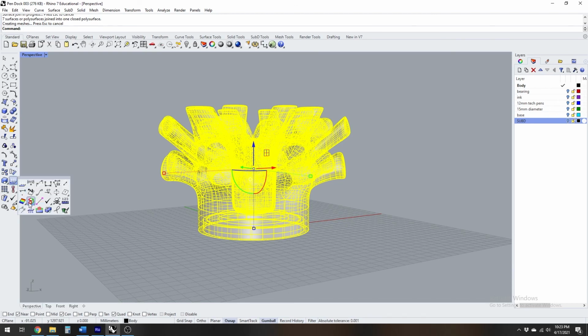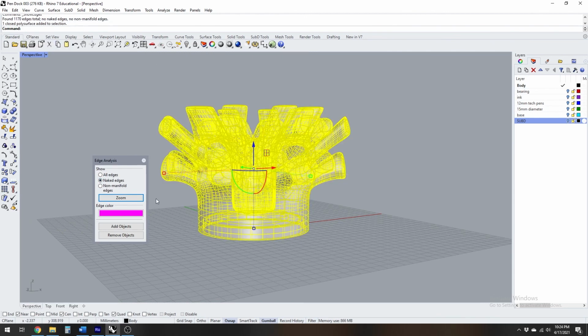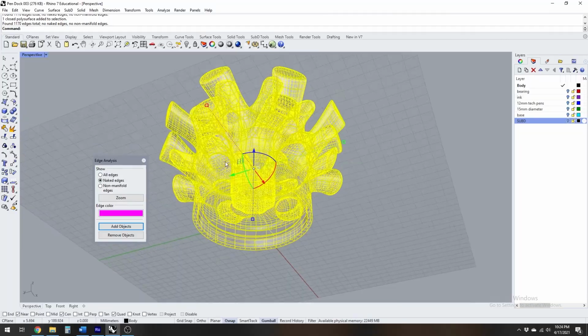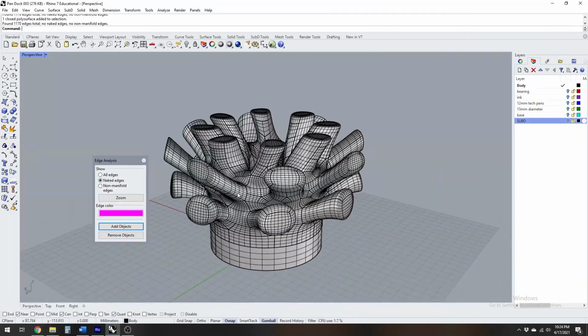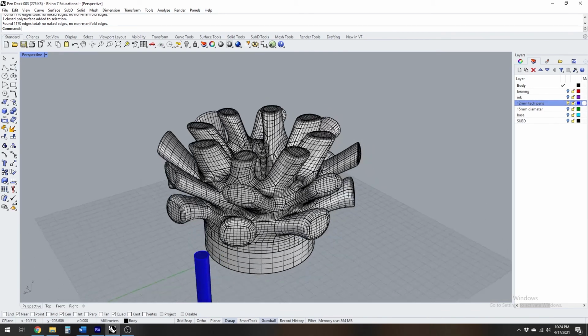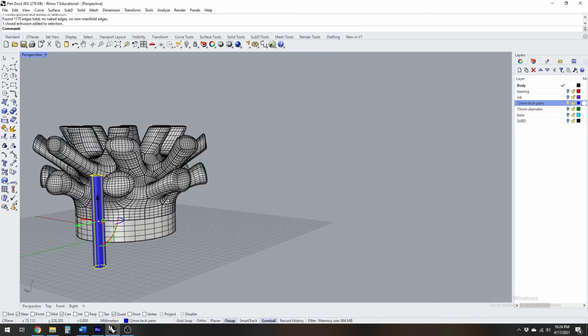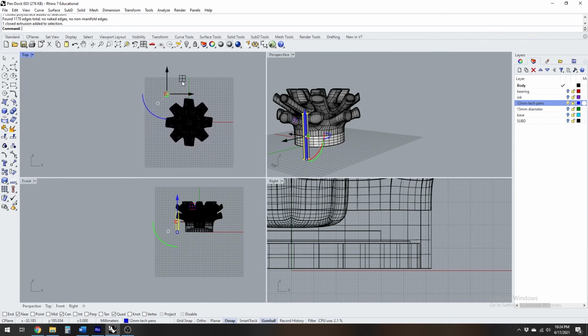And you can see here with the join, let's do some edge analysis. If it doesn't 3D print, it ain't worth anything to me. You can see we have 0 naked edges, 0 non-manifold edges as well, and that's even after this join. So we're going to cut some holes and then we'll analyze again. But I can tell you that so far, within the realm of reason, I've been able to push this pretty extensively, and the surfaces remain airtight. So one-click 3D printing is not a bad thing for highly organic surfaces.